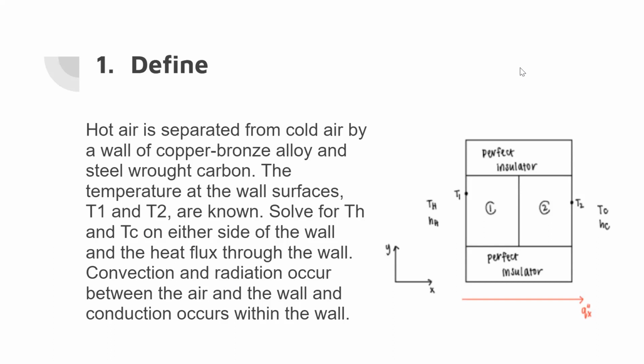So this problem relates to the resistance model because it has parallel and series. It has convection and radiation, and the series circuit is going to be conduction through the wall. The total is heat transfer from hot air through the wall to cold air. This is applicable in any system where heat transfer is 1D. Composite walls are applicable in chemical reactors, which is what these are.